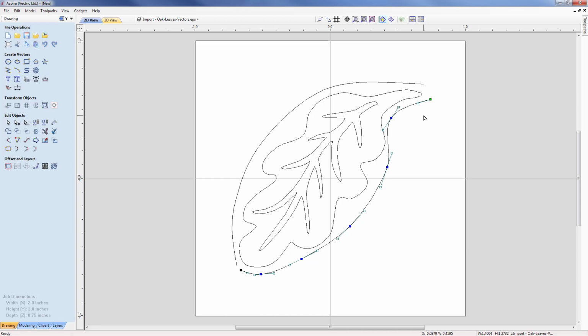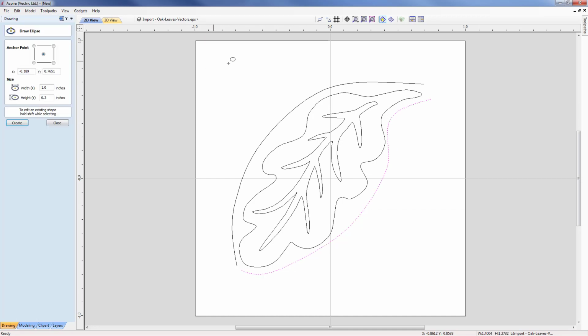Okay, so with that, I now want to move into creating the profile that will be the cross section for the 2-rail sweep. So I'm going to go across to the ellipse command and just basically stretch out a shape now. So we're going to stretch out a shape that happens to be 1 inch in width, and we're going to go a height of 0.3. So I'm just using the smart snapping to get that size.